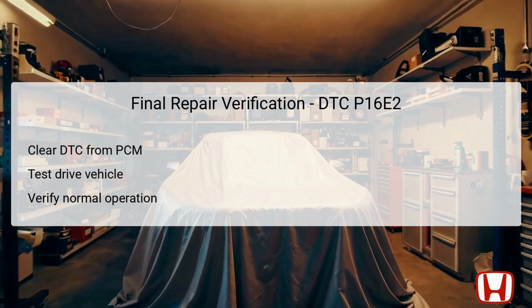After clearing the code, a test drive of the vehicle should be performed to enable evaluation of its performance under various conditions. During this drive, technicians need to remain vigilant for any warning lights or irregular operations that could signal remaining issues. If the vehicle operates normally without triggering the P16E2 DTC again, it indicates that the troubleshooting guided the repair process effectively, ensuring a successful resolution of the initial problem.